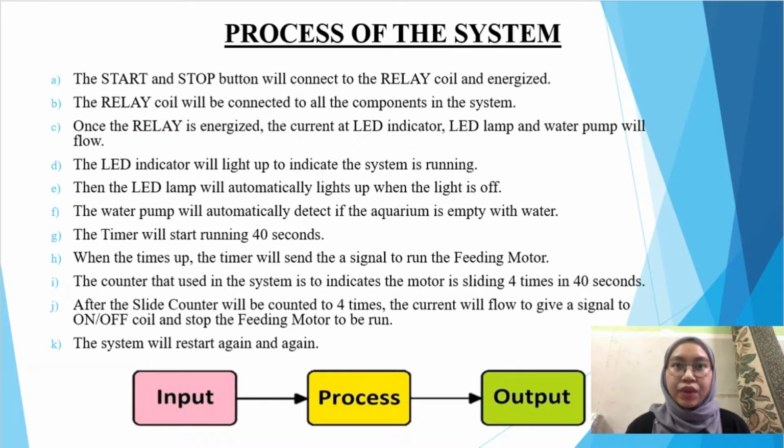We are using counter 2 in this system. The counter is used to indicate the motor is sliding up to 4 times in 40 seconds. After the slide counter has counted 4 times, the current will flow to give a signal to the on and off coil to stop the feeding motor from running.